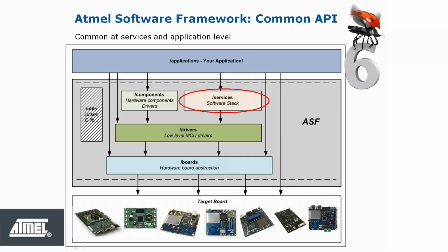The functions called in the example code may need to be modified, finding valid values using the intelligent editor and the ASF documentation. Certain services or drivers have associated configuration files. In this case, we may also need to find example projects to find configuration settings close to those of your application.